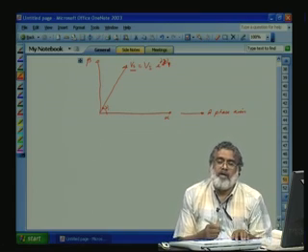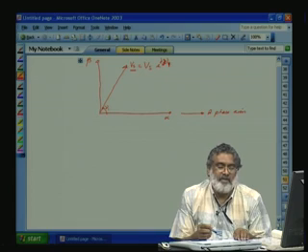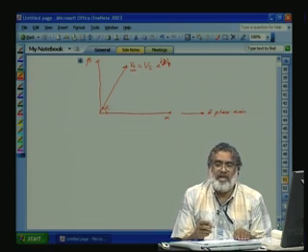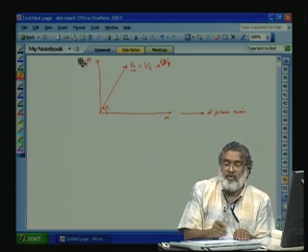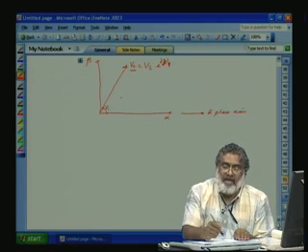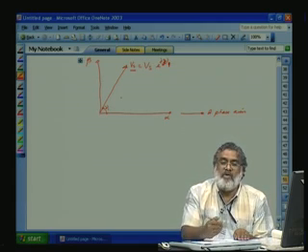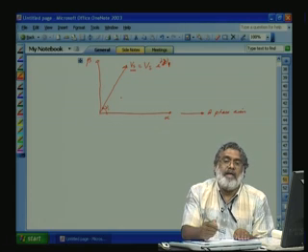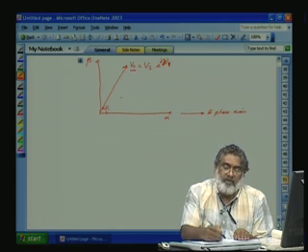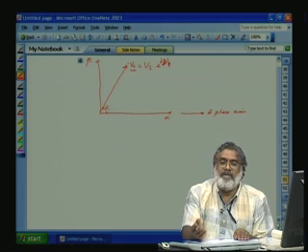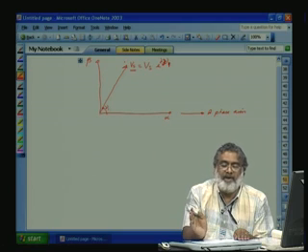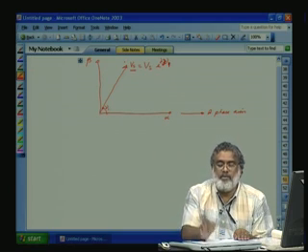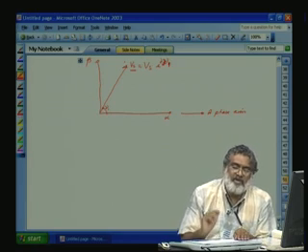Now, assuming the machine is excited with a sinusoidal supply, this voltage space vector has an alpha component and a beta component. Also, the projection of this Vs along the ABC axes will give the instantaneous values, or the excitation values, for the ABC voltages. So, if you know the instantaneous position of Vs and its magnitude, we can find out alpha, beta as well as ABC. So, we do not require the three phase quantities. Here one quantity is sufficient, that is the voltage space vector, in polar form: the magnitude and the angle with respect to the alpha axis.